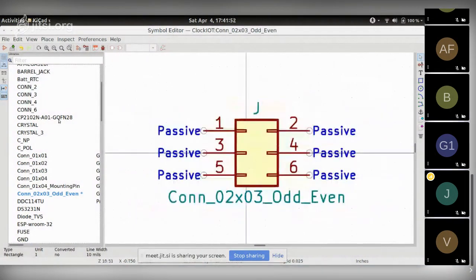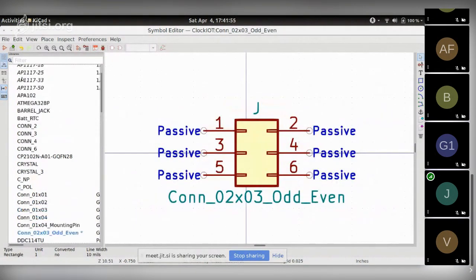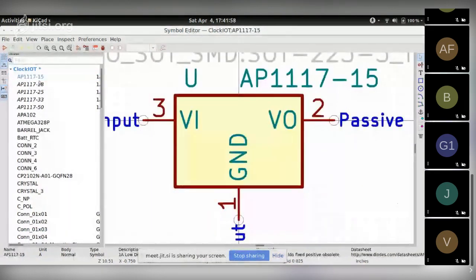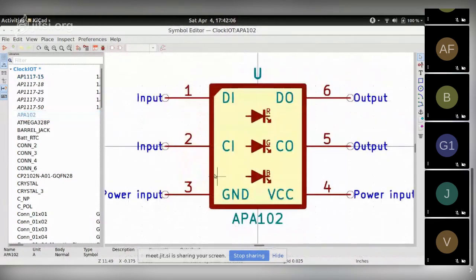Let me show you the library since I'm here. So all of the parts, that's a voltage regulator with a background and a thicker outline. These are all regulators. That's the smart APA102C, the NeoPixel. I've put a marker on pin 1 because with some devices, for example, if you take the WS2812B, the notch is on pin 3 on the device, so it kind of helps to get that cleared out over here.